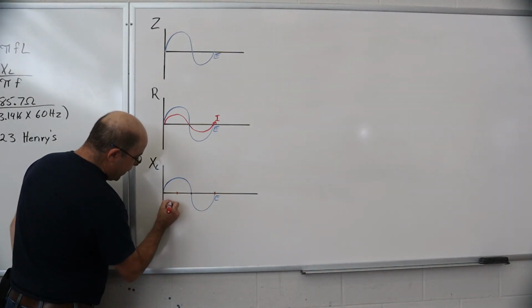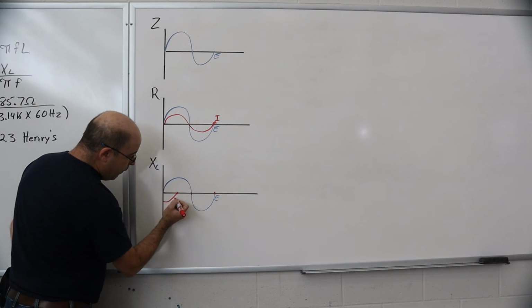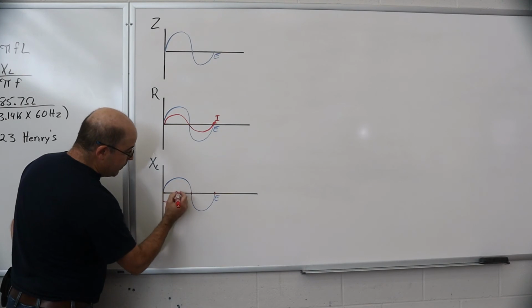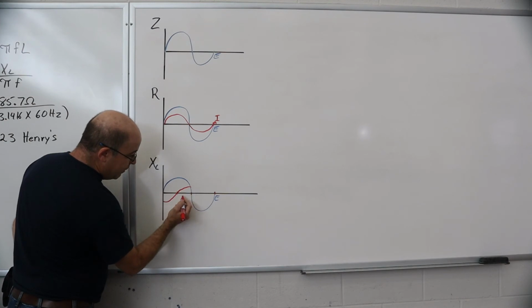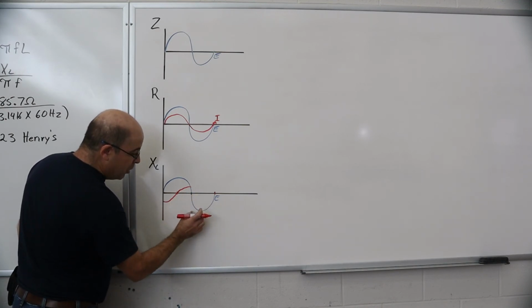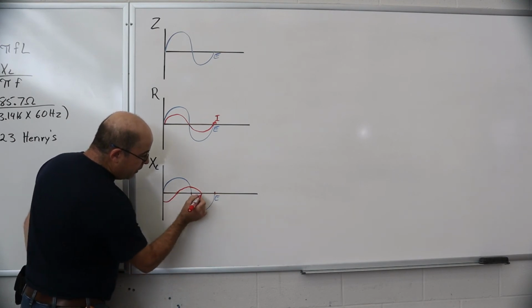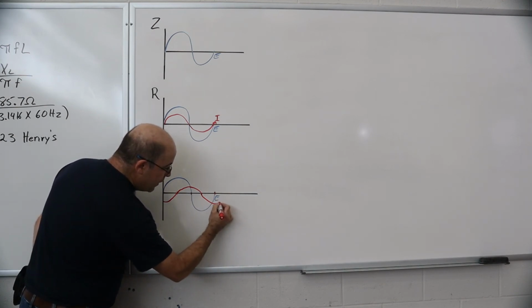So we're going to come down here, and then where we're at our peak, the current will be at 0. When the magnetic field of the voltage waveform starts to collapse, this will start to gain strength and will peak when the voltage waveform is at 0. And then as this waveform goes into the negative alternation and the continually expanding magnetic field is starting to gain strength, the current waveform is going to lag behind and it starts to drop. And it'll cross over at roughly 270 degrees and continue on this same pattern. We are going to identify it.